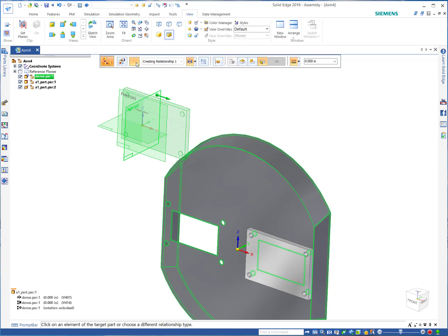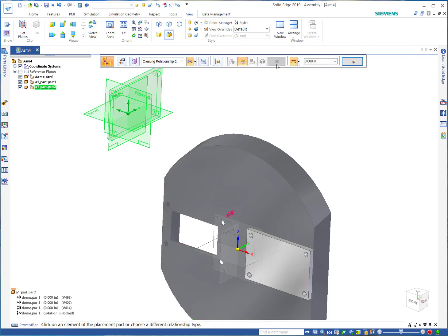Now I've selected my target part and I can choose to have reference planes, sketches, whatever it is that I may need enabled to do the job. And then you do have that OK button at the end, which is kind of nice. It slows the process down. You could change your options to maybe a floating mate or a range, and also give it your offset. And then you just either click OK or right click in the screen space, and then that step is finished.